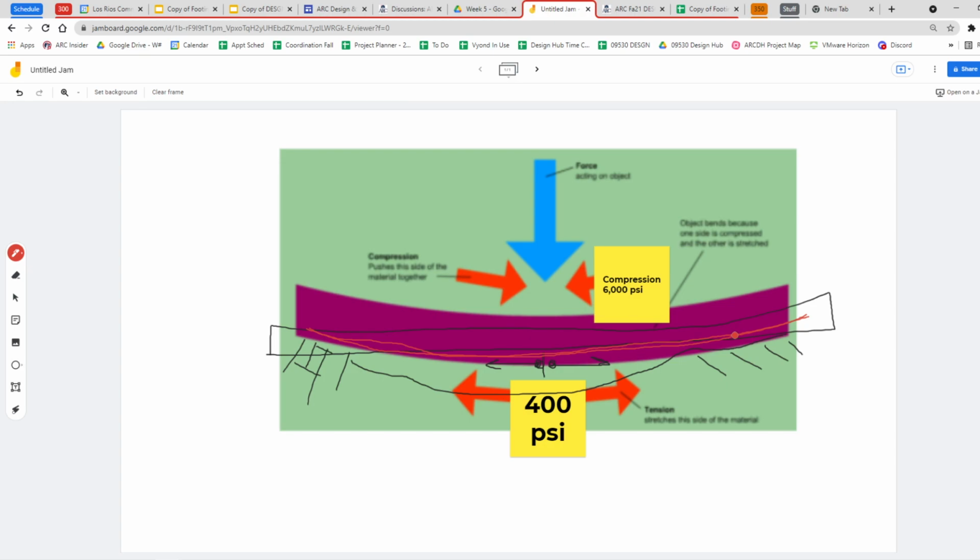And that's standard rebar. If you tension the rebar to begin with, the rebar actually squeezes together and puts it into compression here. But most foundations are just laid in standard rebar, and it's there to prevent the crack that's going to start at this very bottom spot from going all the way to the top and having your foundation break in two.